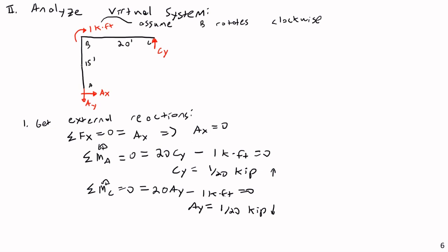So what I'm going to do is get m as a function of x first by cutting this here, and then by cutting this here. I'm actually going to isolate this piece of the beam and this piece of the column. Then I don't have to worry about drawing the free body diagram of the whole exploded view. This one's going to be fairly straightforward because we just have x from the end. This one will be a little bit more complex because we have x from this end, so that'll take a little bit of doing. But let's do that.